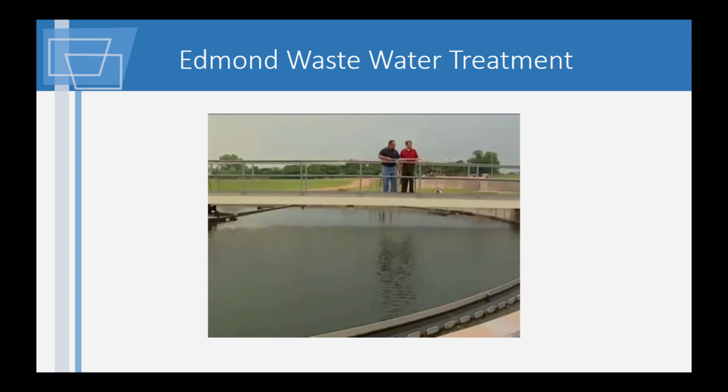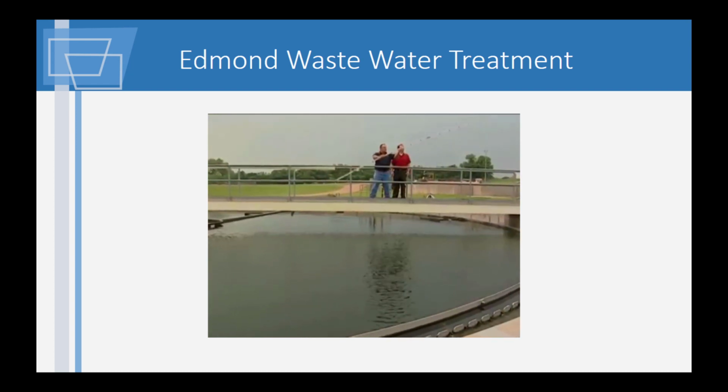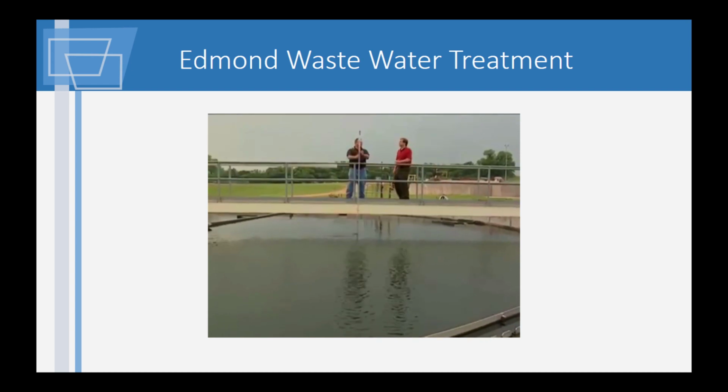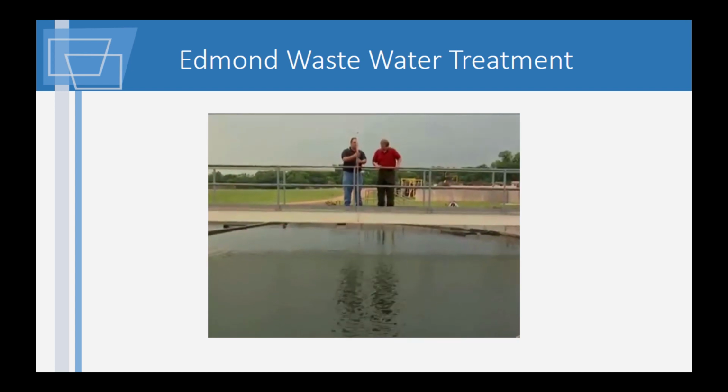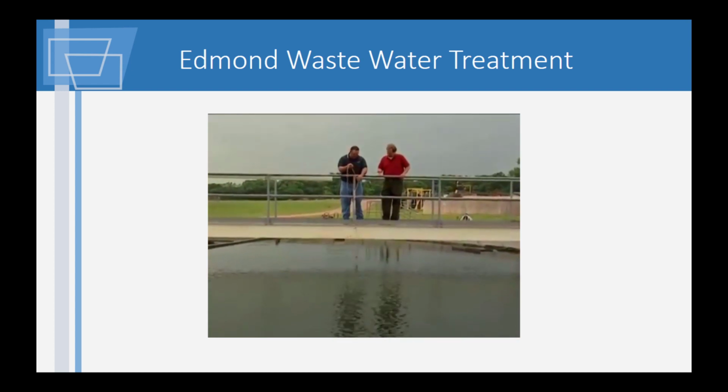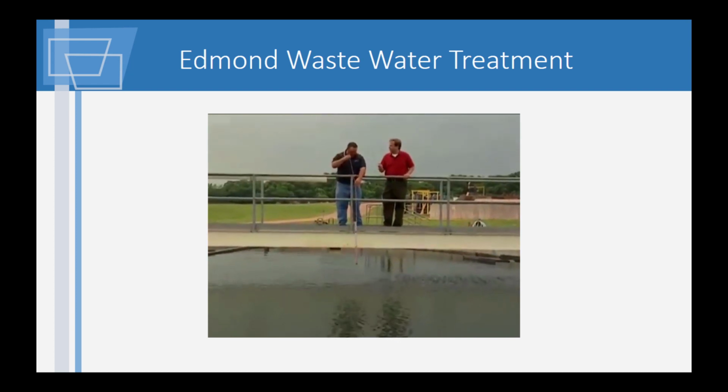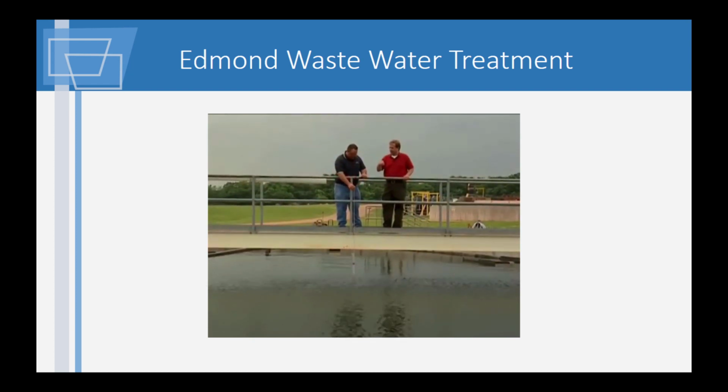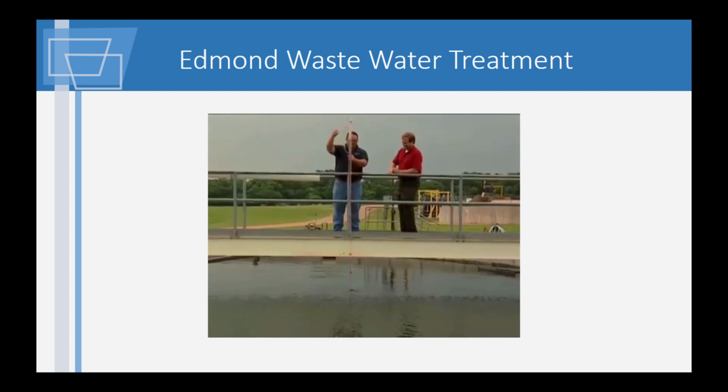Okay, now what is this? It's a big long plastic tube. We call it a sludge judge. It takes a core sample of the water, so we can see exactly how much. You run this down to the bottom, just like when you're a kid, you get a straw and you put it in your Coca-Cola and put your thumb on it and pick it back up. Same concept.